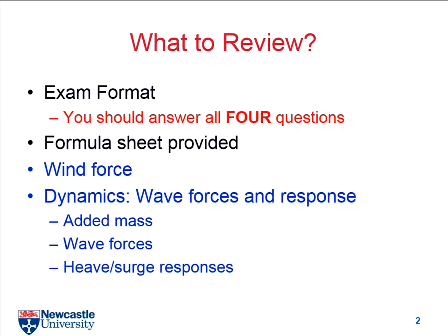Actually, if you go through all the materials in my part, we just focus on 3 or 4 points. If I do a summary now, I would like to introduce the Morrison's equation first. And actually, when you finish all the calculation cases, you will find that no matter when you try to find out the mean force or the wave force, all of them are based on Morrison equations, but they use different terms.